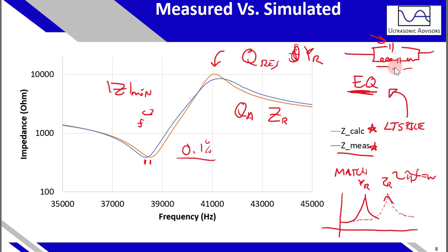Now, the sharpness of this peak is obviously different between the measured and simulated values, based off of parameters calculated from the resonant frequency. So there are physical differences, likely in the damping factor. If you changed this resistor, you would likely fit the calculated and measured value more accurately, but there are, as clearly shown, physical differences in the damping factors in these two situations.